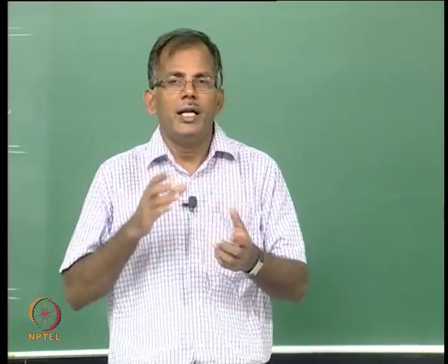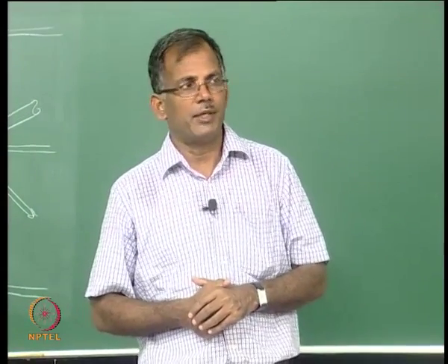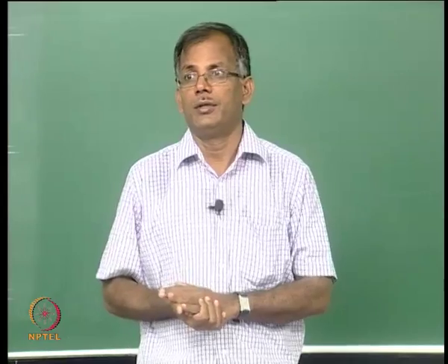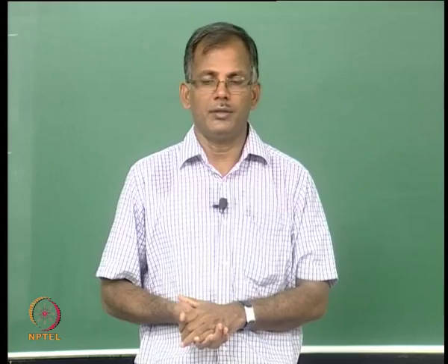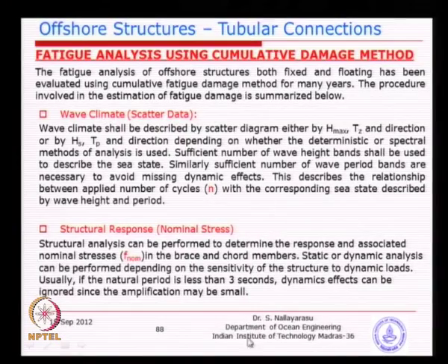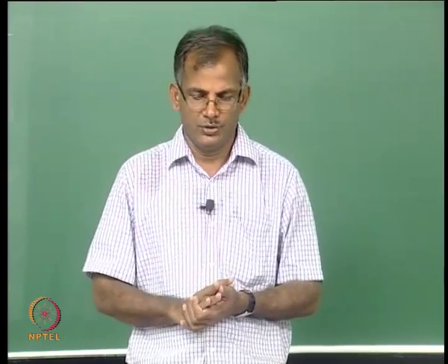So, this is where a little bit of difficulty comes, because you have to actually get this prediction correct, otherwise all your calculations are not going to be correct. So, the wave climate is basically the description of your sea state conditions, either short term or long term. The next one is the structural response, which is very easy, because all of you are civil engineers, you can calculate the stress applied on a structure by means of static or dynamic analysis, which is very easy.